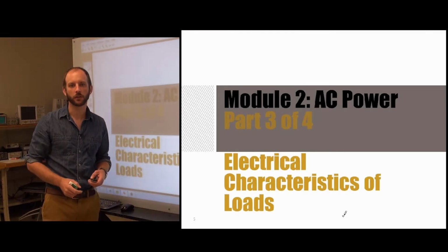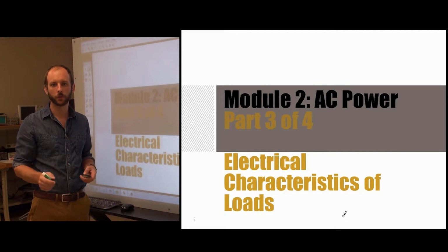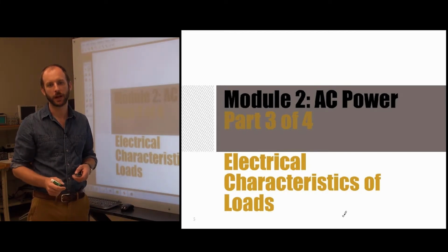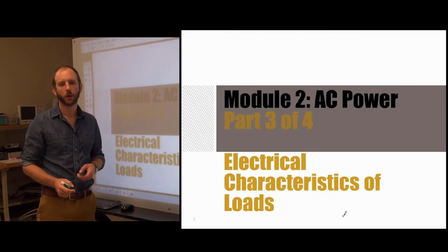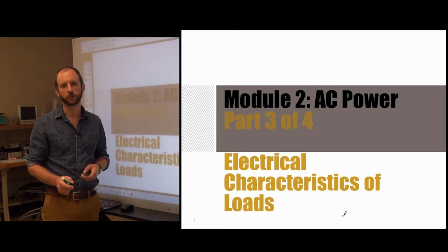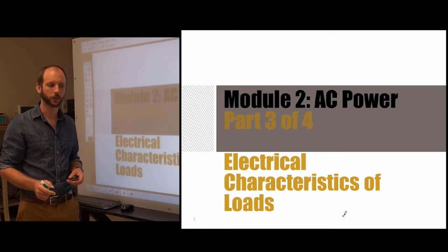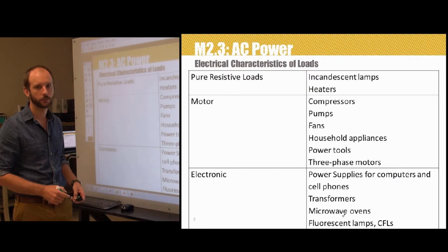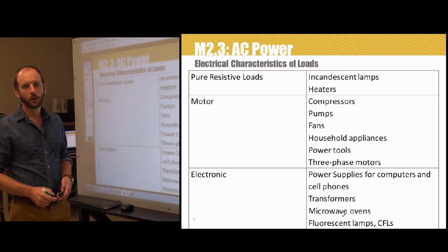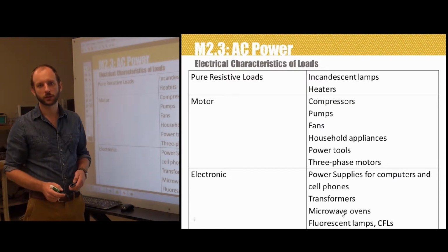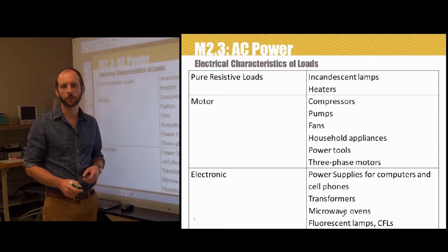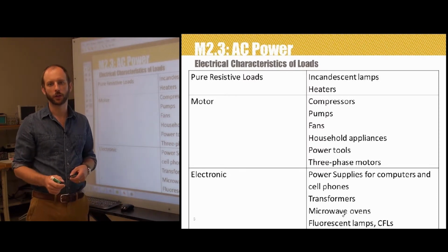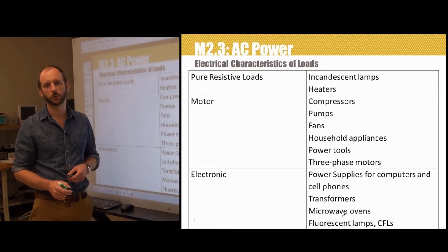Again, in the context of electrical circuits, the term load refers to any device in which power is being dissipated or stored. From the circuit perspective, a load is defined by its impedance, comprising a resistance and a reactance. The impedance of actual electric devices may be fixed, as in the case of a simple light bulb, or it may vary, for example, if an appliance has several operating modes or settings.